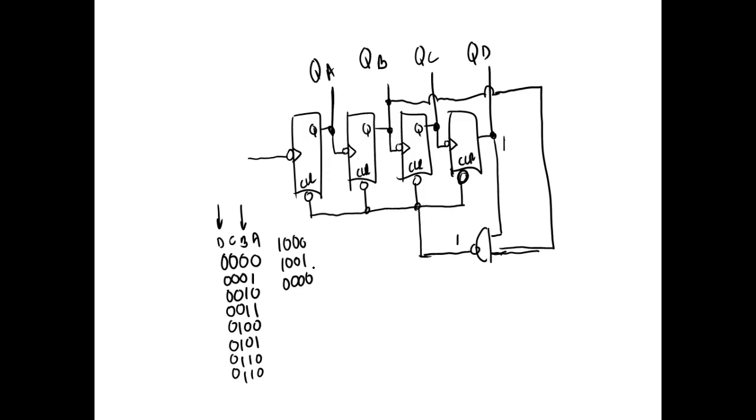Yeah, this is a BCD counter. If I look at the circuit of a BCD counter, all they do is exactly what they do here. I could convert any binary counter into a BCD counter just by resetting it on what? On 10. We're actually resetting it on 10, right? You understand? As soon as it goes to 10, the output goes to 0 and we'd never see it.